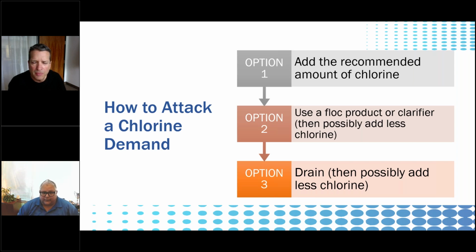It does not cause a problem. You can add shock products to that pool in order to help overcome the problem. Option two, you can use products like flock products, clarifiers, phosphate removers, anything that will physically take out debris. And then ultimately, you're still going to have to add chlorine, but you'll probably end up adding less chlorine to the water. Or you can do a partial drain and refill.